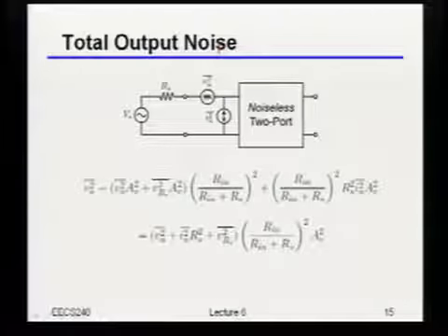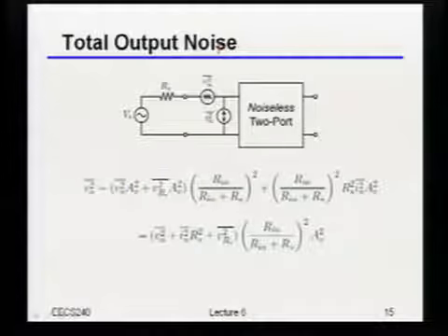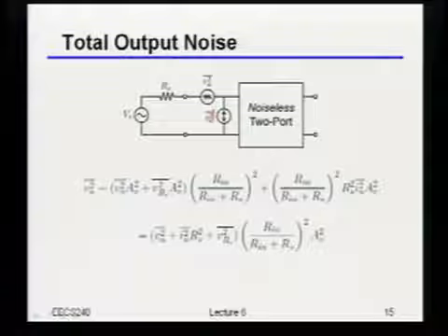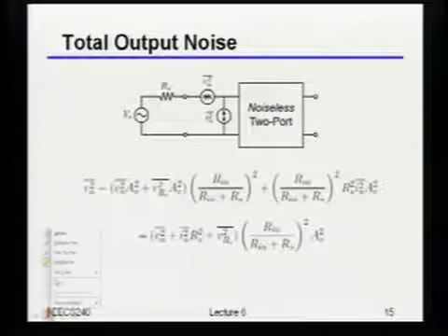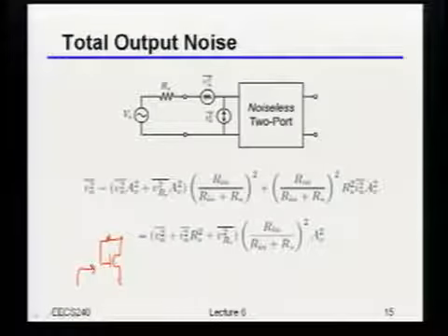As an example, if I had a bipolar junction transistor, and I have some noise at the base, that's going to translate into noise at the collector. So if you worked out the equivalent noise generators, you'd actually have some correlation there. Usually people ask how exactly that correlation happens. It's a function of how the circuit is built.